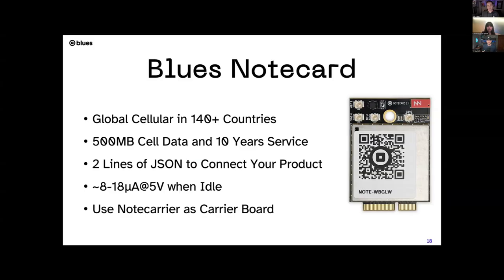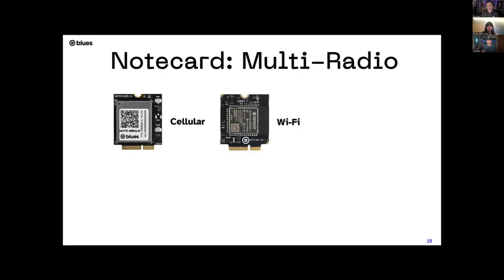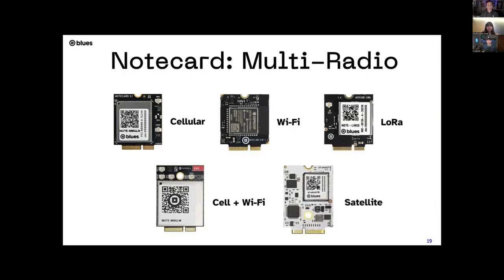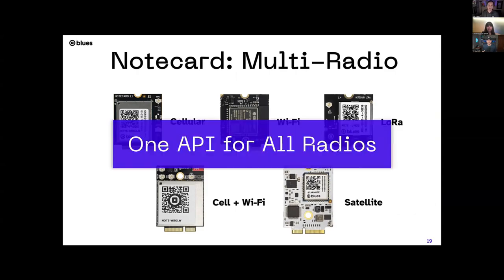It also uses the aforementioned Notecarriers as that interface or as a development board for working with your chosen host MCU. Now, I mentioned this, but there are plenty of Notecard options depending on the radio that you need to use. Cool thing is they are all swappable, both in terms of that physical connector, that M.2 connector at the bottom, and the fact that you only use one API the same way to program all your Notecards. So this allows for truly mixed deployments, like mixed radio deployments, with one set of firmware running your multiple fleets.